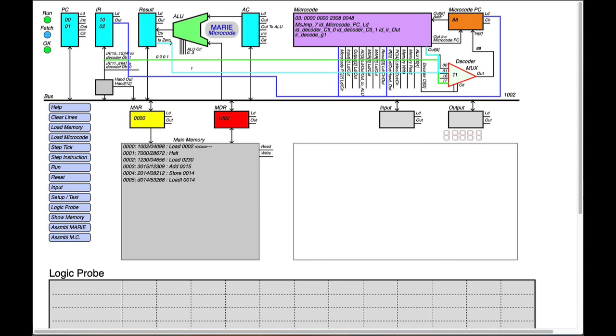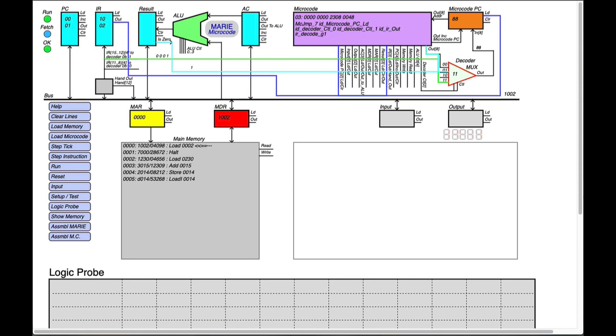And I've also given you the addresses for all the other instructions as it decodes them, which actually turns out to be fairly hard and annoying to get right. So all the instruction addresses are here all the way through the microcode. Down at the bottom of the microcode file that I'm supplying you are some comments that say this is how the different instructions work, this is what the opcodes are for the instructions, and also over here there's the ALU. It has the table of what inputs you give the ALU to get what results as an output from the ALU. So there are some comments in there after the end marker in the instructions.